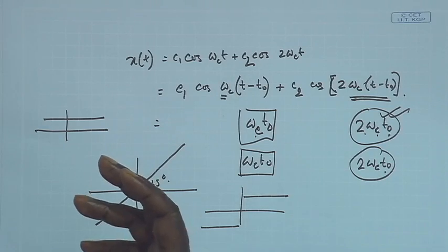Both a delay element and a Hilbert transform shift different frequencies, either with different phase, or this one gives the same phase shift, and neither touches the amplitude. But there is a certain difference, and that is why whenever you do a Hilbert transform you will have a deformation of the signal, whereas when you provide a delay element you will never see any deformation of the signal. This is the basic difference between these two.